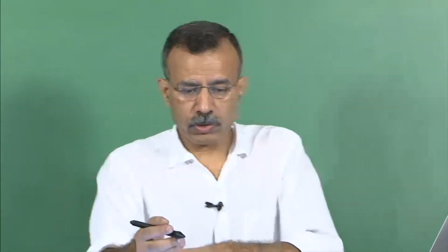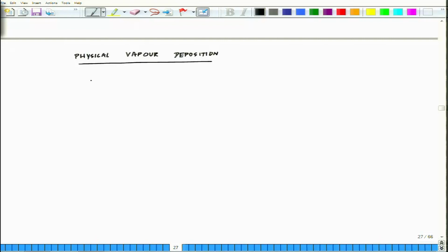Okay. So coming to the physical vapor deposition, which is also called PVD, it is an environmental friendly vacuum deposition technique consisting of three fundamental steps. So you realize that you need conditions of vacuum in such situation, and the first thing is vaporization of the material from a solid source.